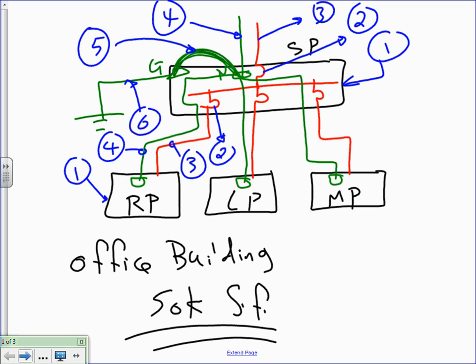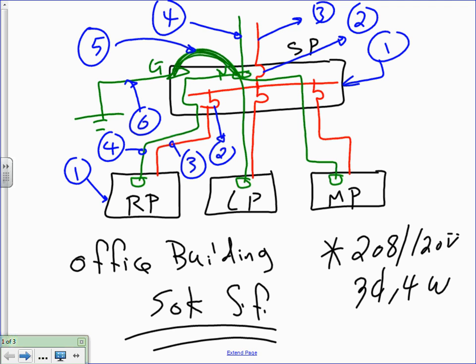And the system that we're using, this information is very important. We're using a system of 208/120 volt, 3-phase, 4 wire. Very important, guys, to specify what type of system you want to power this building, because I could use 480 and it changes the whole calculation. So put this right next to the one line diagram. You're going to see the calculation goes fast, guys, because you did it with math. It takes longer to write the information than to do the calc, really. Okay.